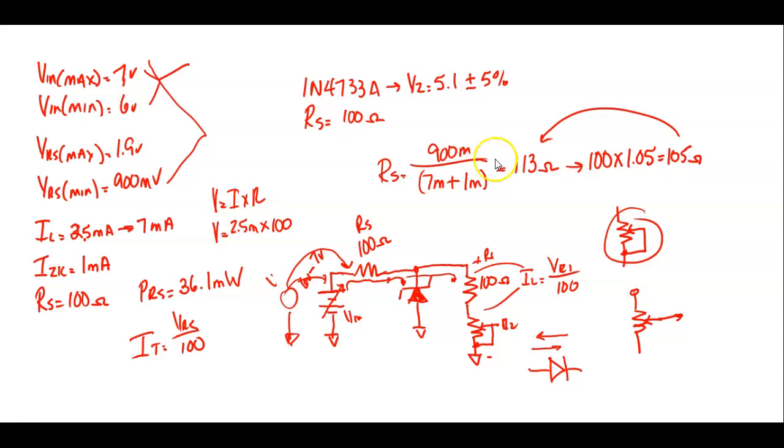Okay, y'all understand. What we're trying to do is get 2.5 milliamps to flow across that resistor, because that's my load current, right? But I'm going to measure voltage. So what do I need to calculate voltage? Using Ohm's law, voltage is equal to what? I times R. What do I know? Well, I know the current I'm trying to get. I'm trying to get 2.5 milliamps. What size is the resistor? 100 ohms. So when this resistor drops this voltage, that means there's 2.5 milliamps flowing through it.